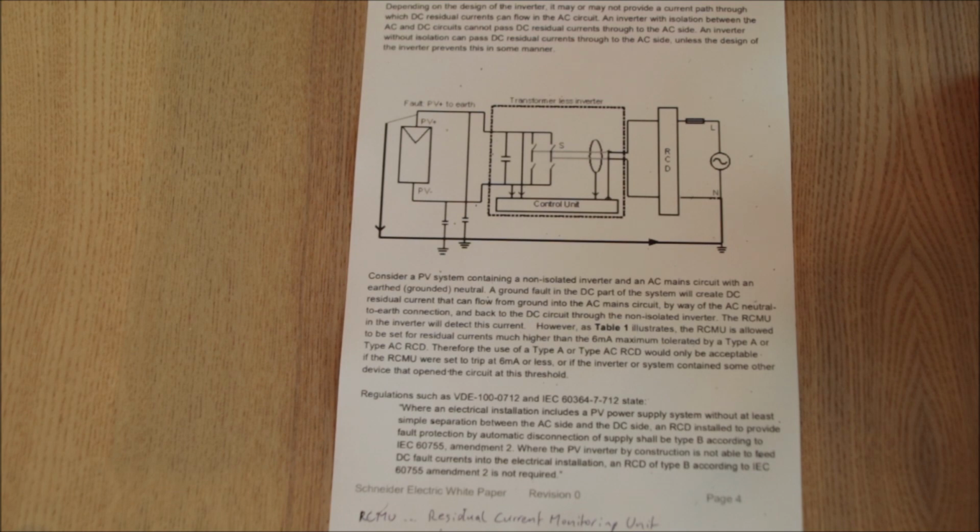Every off-grid inverter which is a low-frequency inverter, those have these massive transformers built in, will most probably be a transformer-based inverter, which does not have this problem. And for those high-frequency inverters, you would really have to find out from the manufacturer what sort of design that inverter has and if this applies, as a transformerless or a transformer-based inverter.